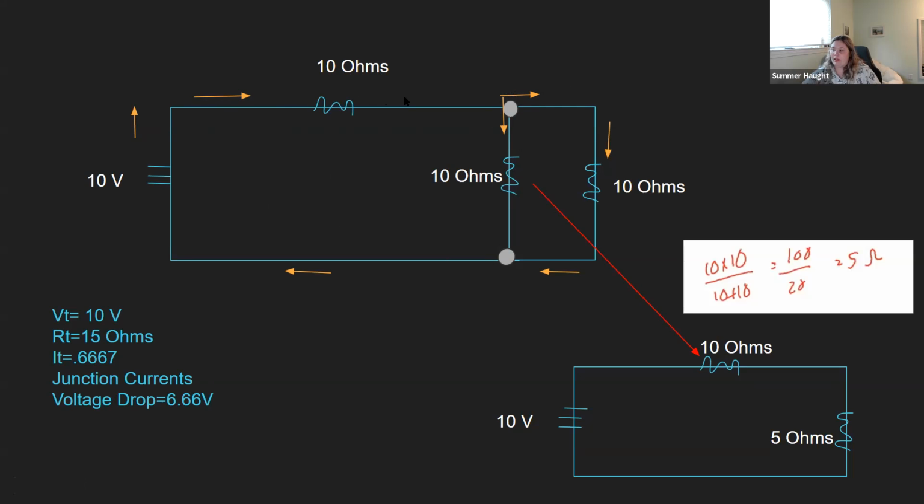So, let's say the current going into this junction is 10 amps and we have 6 amps going here. We know that we have 4 amps going right here because it has to sum, because when they meet back up here, we have the 6 and the 4, so it can equal 10, and then we have 10 amps, which is what we started with. Same thing with voltage drops. Whatever the voltage drop is here, right on this line, it splits up right here, and then it should sum back together right here. So back to this problem.